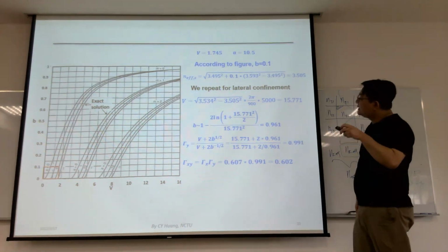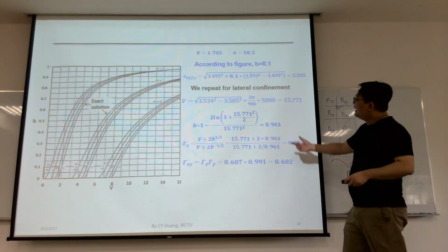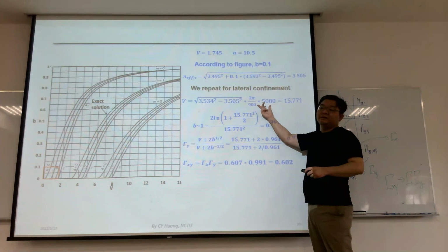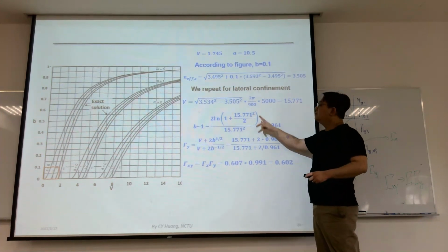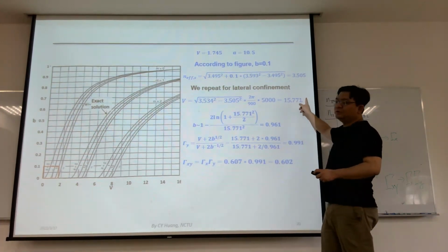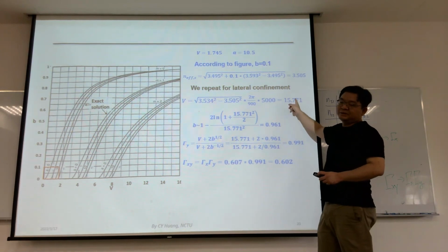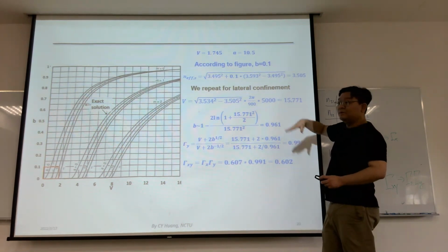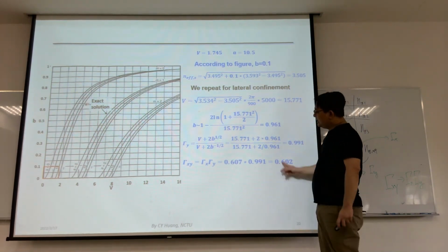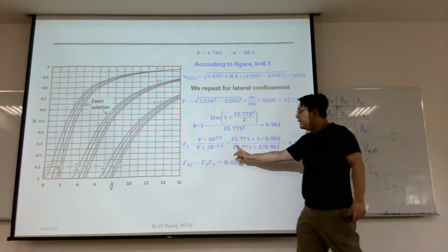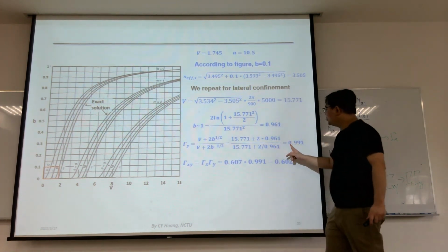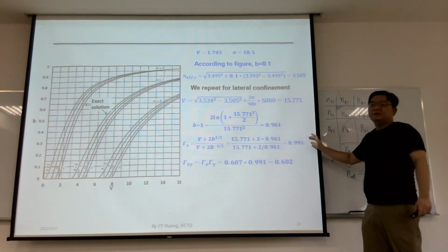And we see that because you have a pretty wide ridge for the common ridge waveguide laser, the V is usually much larger than the vertical confinement. So it turns out the gamma y, the lateral confinement, is usually pretty large.